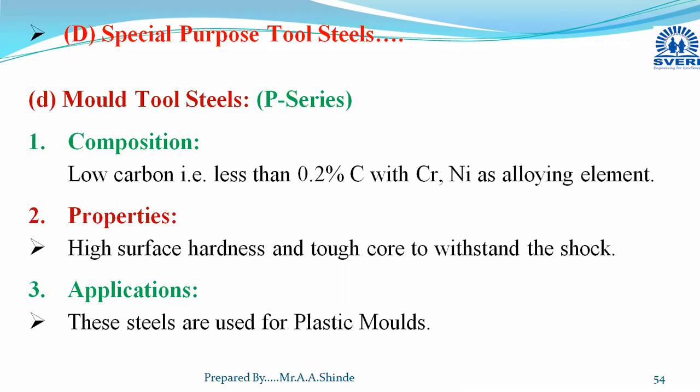Okay, now a generalized statement or one conclusion we can make here related to all tool steels or alloy tool steels, is that whenever we require abrasive hardness or high wear resistance or high toughness or red hardness or non-deforming properties, that is less deformation, then we can use these different kinds of tool steels for that operation.